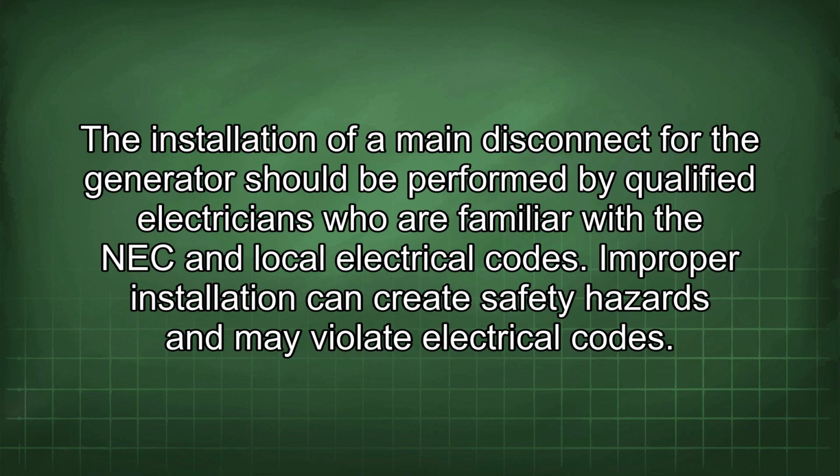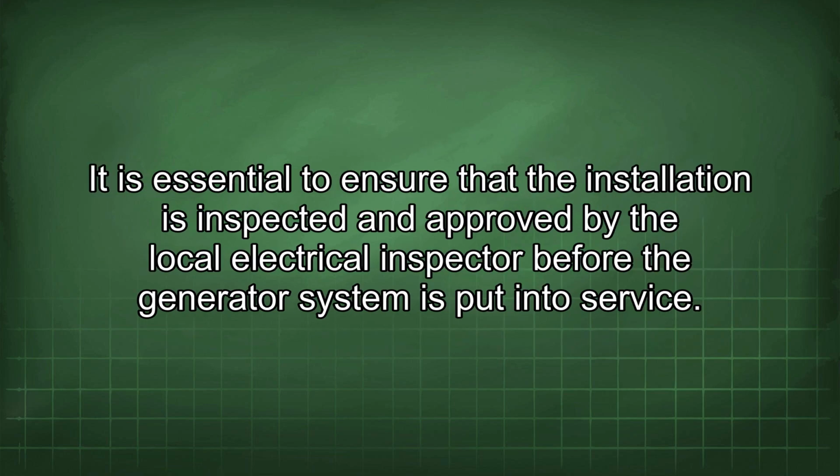The installation of a main disconnect for the generator should be performed by qualified electricians who are familiar with the NEC and local electrical codes. An improper installation can create safety hazards and may violate electrical codes. It is essential to ensure that the installation is inspected and approved by a local electrical inspector before the generator system is put into service.